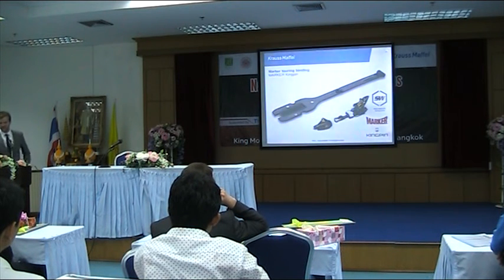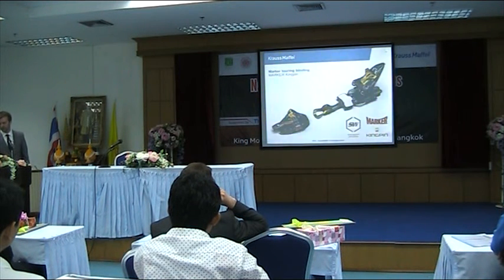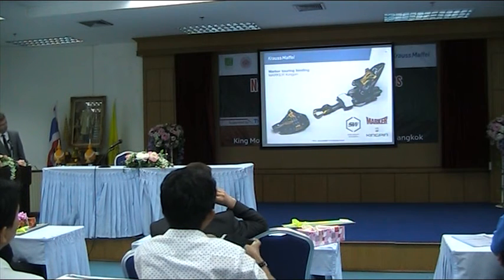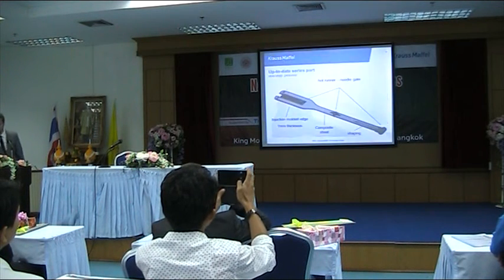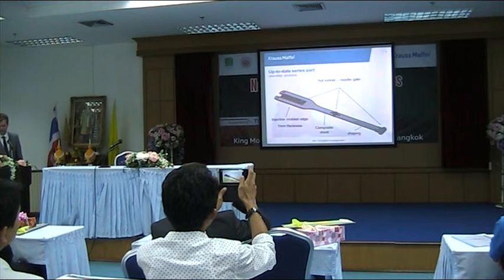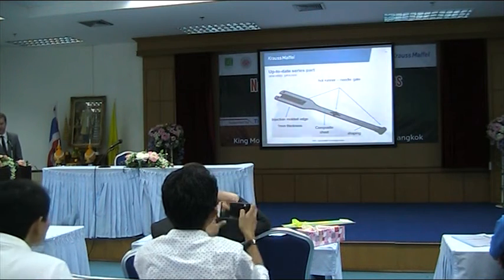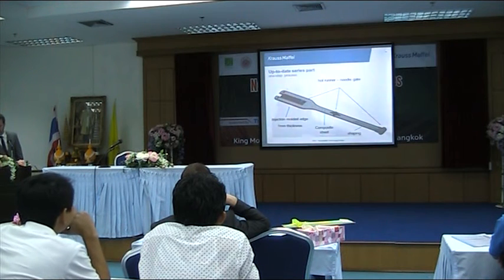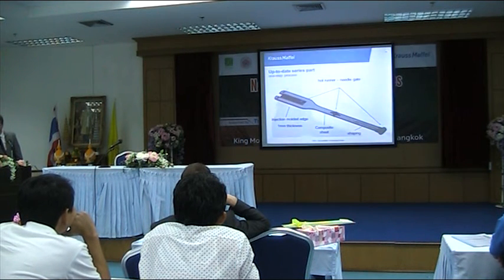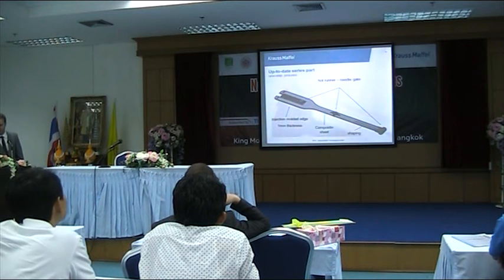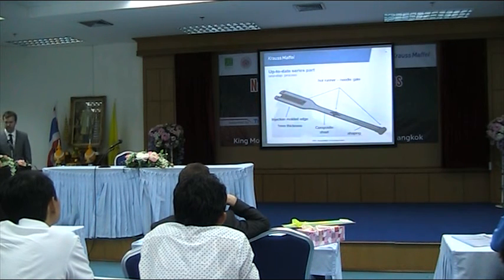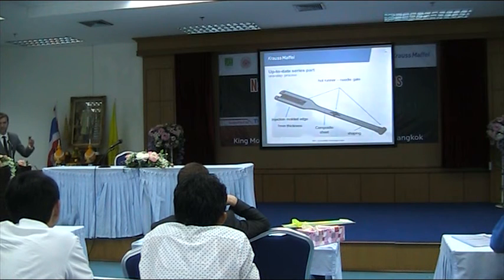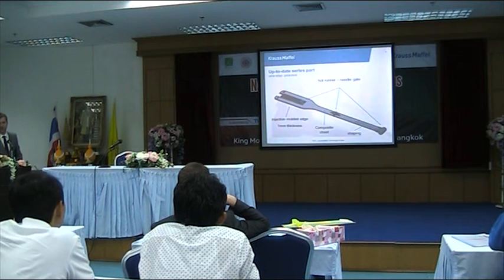And now this goes into high-scale production. So this is a ski binding, and it's only one part of it, but it is not very easy to produce. You have this composite or organic sheet, and you shape it by thermoforming, and you have some edges that are only 1 millimeter thick, and you have a hot runner and a needle gate, and you need very precise placement of the organic sheet for the molding. Otherwise, you will have a failed part.